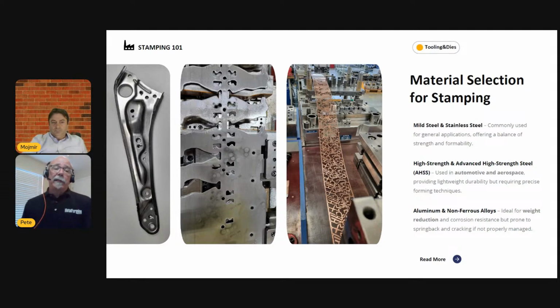Many of these high-strength steels, especially the dual-phase materials, I'll speak just a moment really quickly on what dual-phase means. Most of the steels that we use, our mild steels, our high-strength low-alloy steels, are what we refer to as single-phase steels. If we looked at the microstructural phase under a microscope, what we would see is a ferrite matrix. It'd be all ferrite, iron. And that ferrite is very soft, it's very formable.